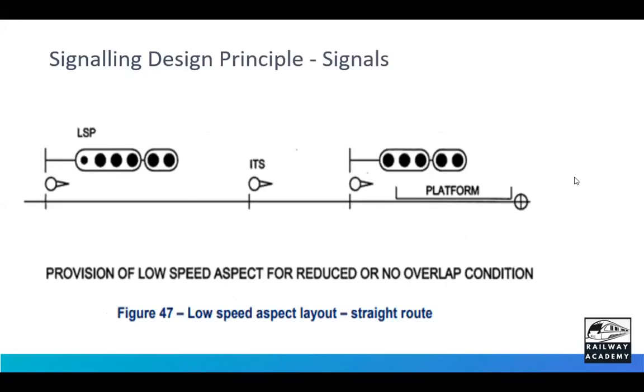Now coming to this arrangement, somebody asked me, what are these switches, sir? Here, they are not switches actually. These symbols are called train stops. The train stop arrangement is somewhat similar to what is called TPWS, for those who have knowledge about the train protection warning system. So these train stops are fitted in slow speed areas. Every area which requires a train stop and which does not require a train stop has been given in the standards: which areas your single light has to be used, which areas your double light has to be used, which areas you have to use the train stop. Everywhere it has been stipulated in the standards itself.